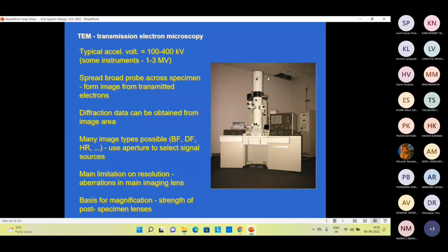So 0.5 nanometer resolution we can attain. If we have a device, let's say a transistor which we are making, in the realm of less than 5 nanometer, even 10 nanometer devices, and we can achieve channel lengths of up to 2 or 3 nanometer, we can see that with this sophisticated electron instrument that we call the transmission electron microscope.